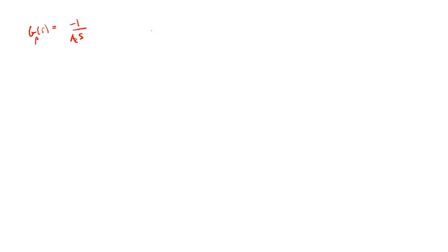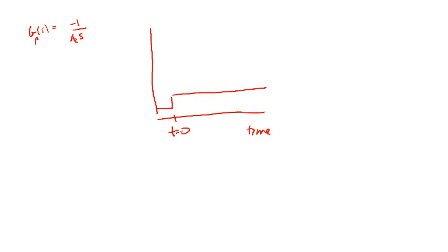So to plot this system, again it's an integrating process, so we have time on the bottom axis. I'm going to set time equals 0 here. We're going to have a step change, and we'll just give a number to that. We'll call that 2. Over on the right axis, we'll call this our FV, so it's our flow rate. And this is just 2 in terms of arbitrary units. We could say 2 gallons per minute.